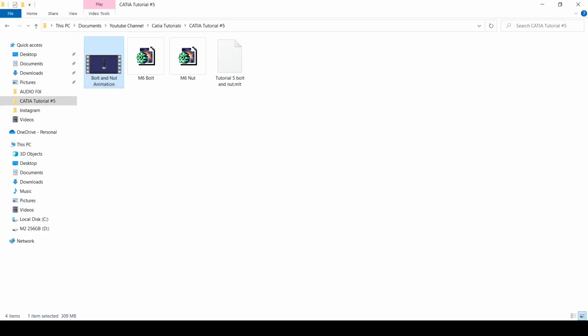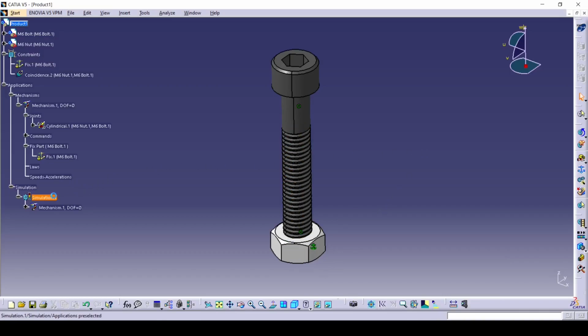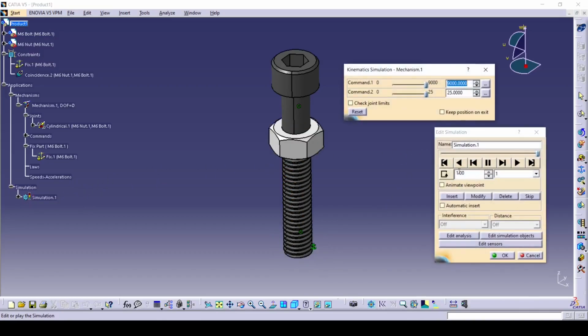Go ahead and close it. And it comes down, double click, to this. Because this one frame is basically treated as 1 second. So this is second 0, second 1. So if you want a slower simulation, let's say a simulation that takes 10 seconds, so you can actually see a nice movement on the nut, you need to create more steps.